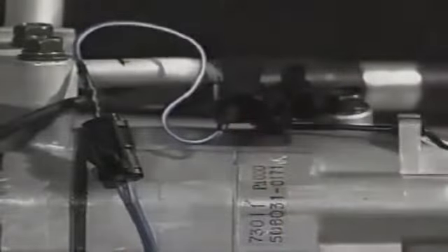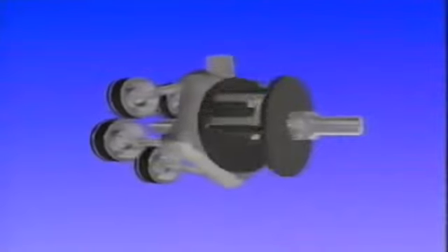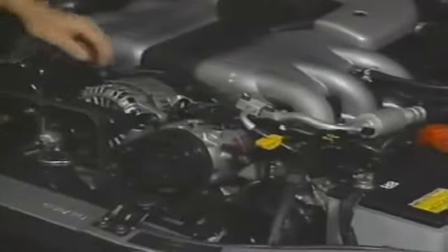Begin by checking the control current at the compressor solenoid. If the compressor solenoid current is correct, the proper air mix door operation or the proper compressor displacement should be verified. Compressor displacement is tested using the refrigerant gauges. Use the output signal recognition mode to drive the compressor from maximum to minimum displacement and note pressure changes.